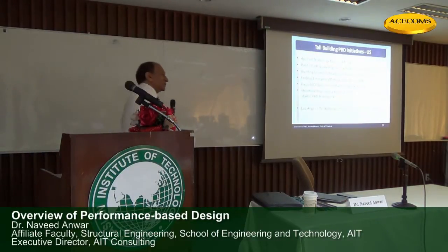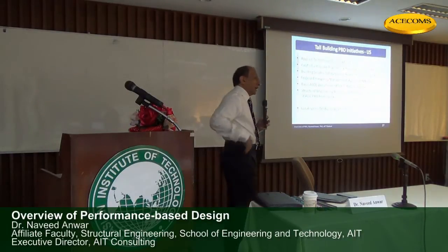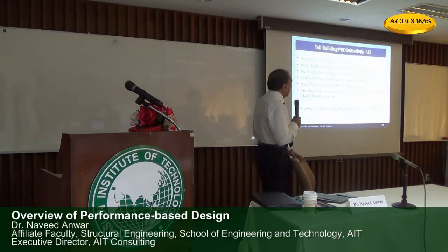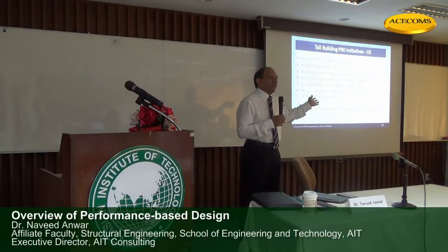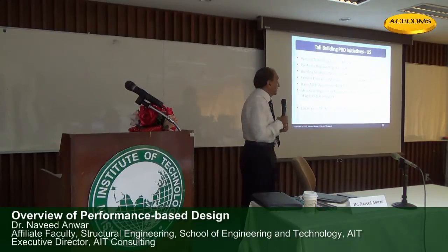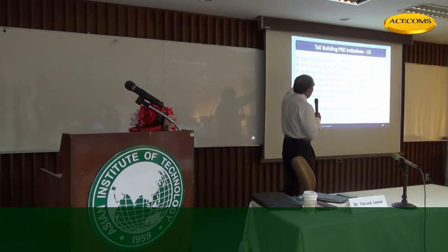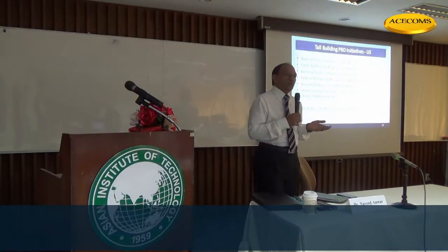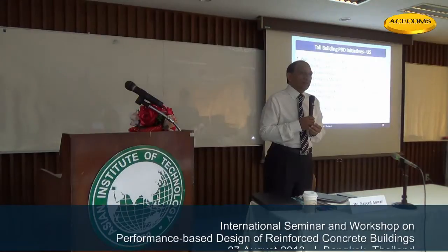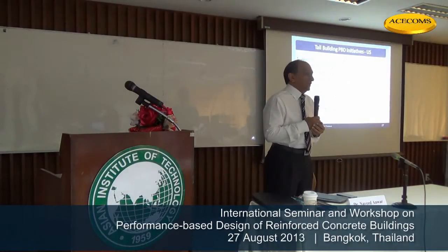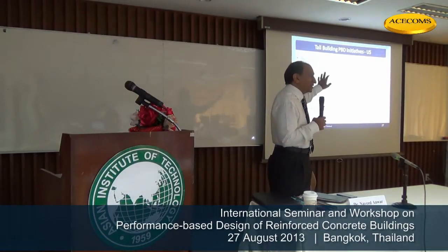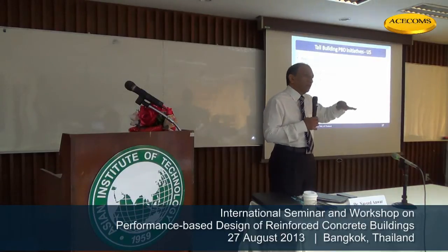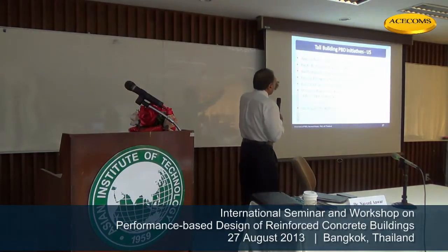For tall buildings, this has now become a more important topic, because for tall buildings, the documents that govern are no longer the design codes. They are not sufficient. They are not applicable. So these are the documents. You can see here, you don't see the ACI code here, you don't see the Euro code here, you don't see the BS code here. The traditional codes are all missing because they don't govern tall buildings anymore. These guidelines do. The engineering community does. So we follow this one.